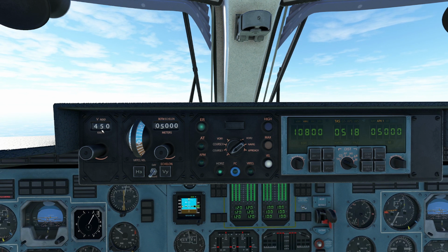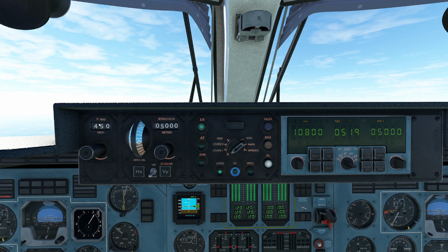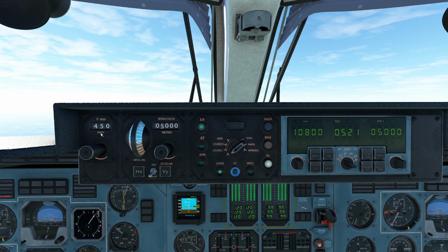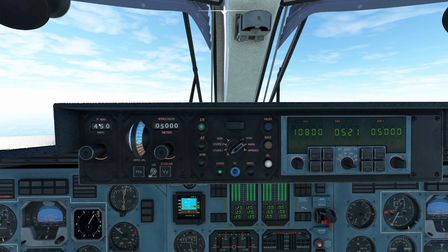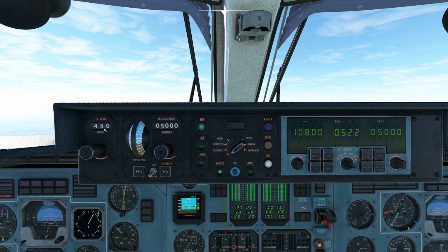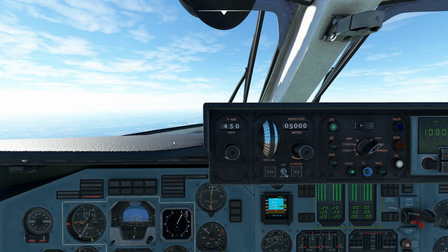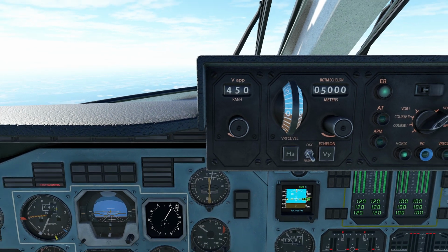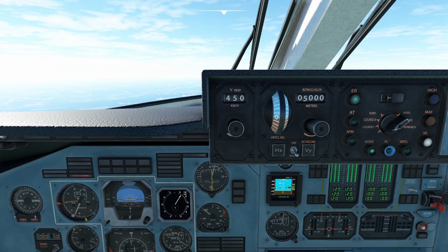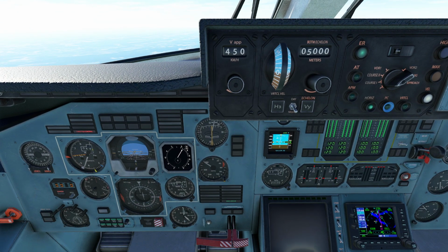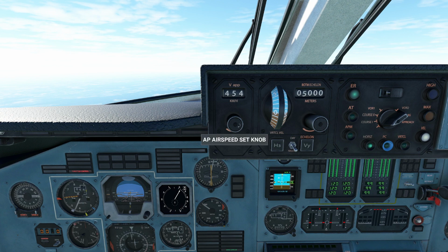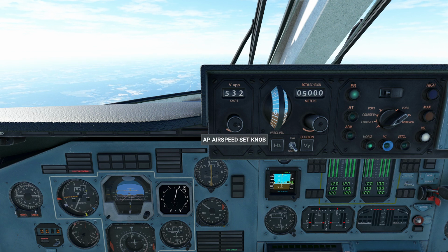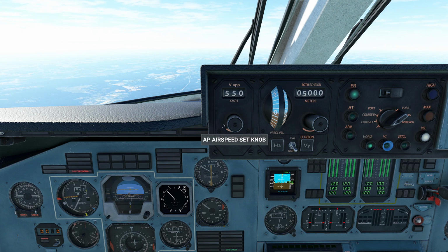Now, the interesting thing here is on Eastern aircraft, it's typical that your auto throttle system is really more for approach, and it's less for just holding yourself at a specific speed during the actual journey you're taking. That's just kind of an interesting little difference that you'll see from time to time. So in this case, I've ordered 450, and I'm actually in a special mode right now, that basically is flight level change. Now, if you're wondering where I got the number 450 from, it seems like an interesting number. That is actually very close to your 250 knots that you're typically supposed to be climbing at if you're less than 10,000 feet. Now that I've gone well past that, I'm going to go ahead and nose down here and give myself getting up to 550 kilometers an hour, which is going to get us a slightly quicker cruise, as you'll see in a moment.